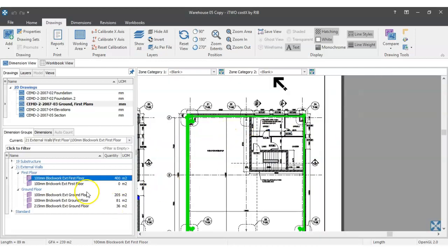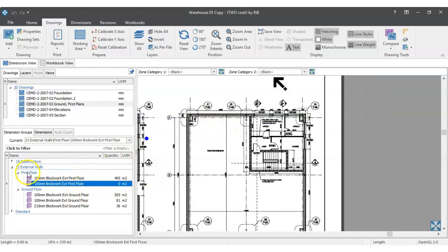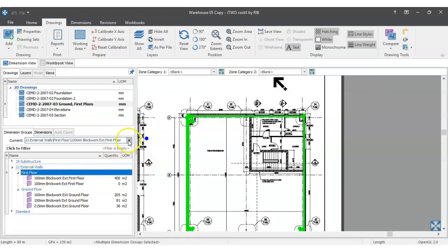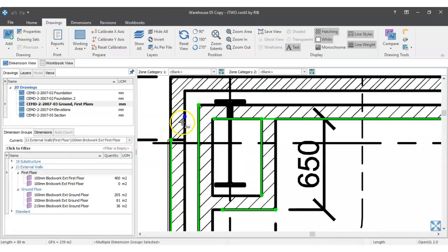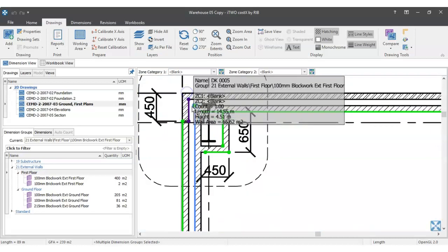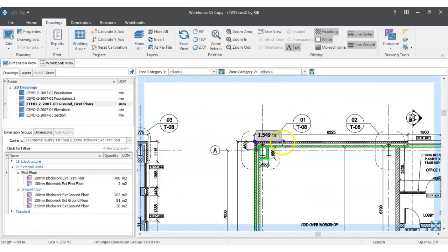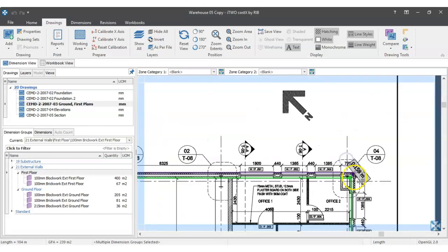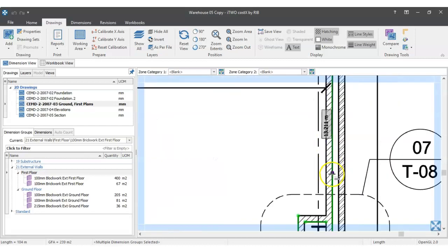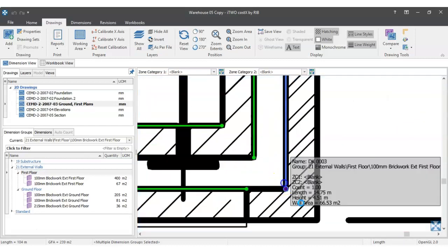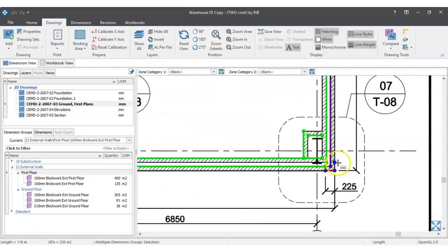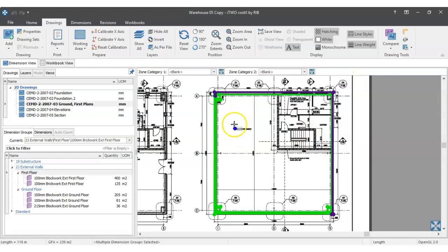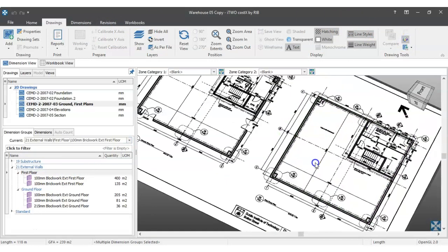I've just the brick facade to measure. And click that. In fact, what I might do is click first floor, use the filter here, drop down, click the brickwork so that I keep that block work open to see where I need to start off from. And the outside, all the way across to here, and this one I believe will go all the way down. I think I'm on the inside still. There we go, and then back to the outside, and that should cover all those external walls on the first floor. Let's take a look at the little 3D, just to see.